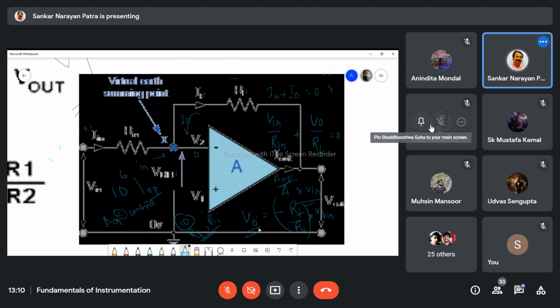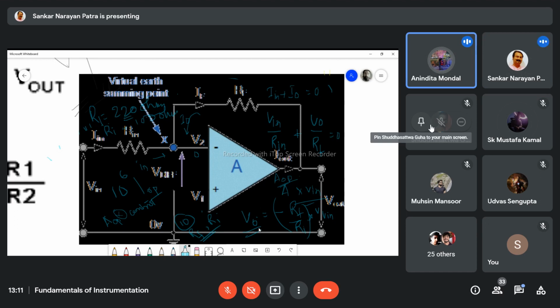If we select Rf equal to 220 ohm, the famous resistance, and Ri is 100 ohm, then what will be the gain? 2.2, sir.